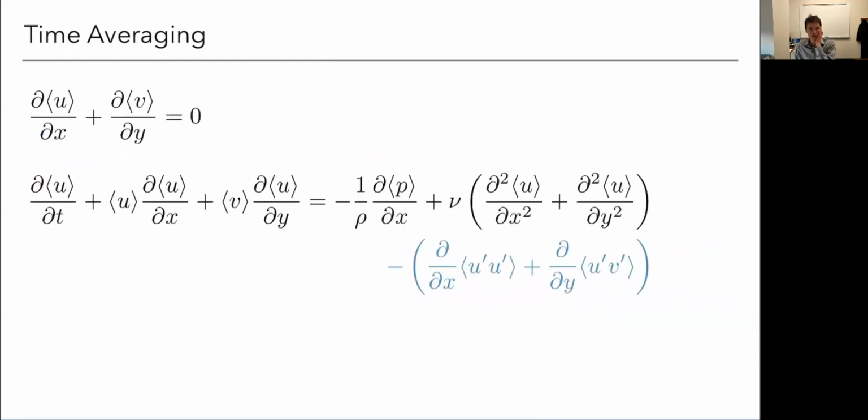And this is what causes a problem for the Reynolds averaged Navier-Stokes equations. I have what's called a closure problem. In other words, I have new terms that I have no equation for. And this is where turbulence models come in. So if you've done any CFD, you've had to select turbulence models, or you've heard about that. Maybe you just use the default, but you probably heard of using turbulence models in CFD, and this is where they come in. Because of doing this averaging, I have these additional terms that I have no model for, so I have to create a new model.